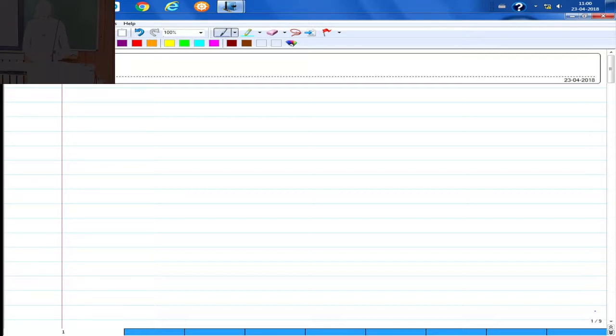So the simple problem is now like you have contact between the two surfaces, so they should not penetrate. So the normal displacement of this surface must be equal to the normal displacement of this surface. If they were just free, you have a different overall assembled stiffness. If you impose this condition, the normal displacement is common to both of these. So accordingly your stiffness matrix actually gets modified.